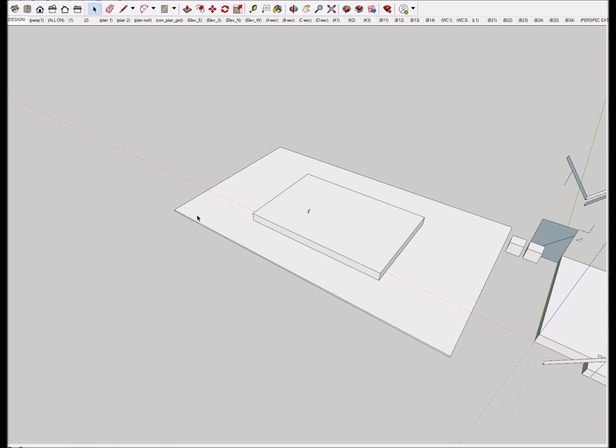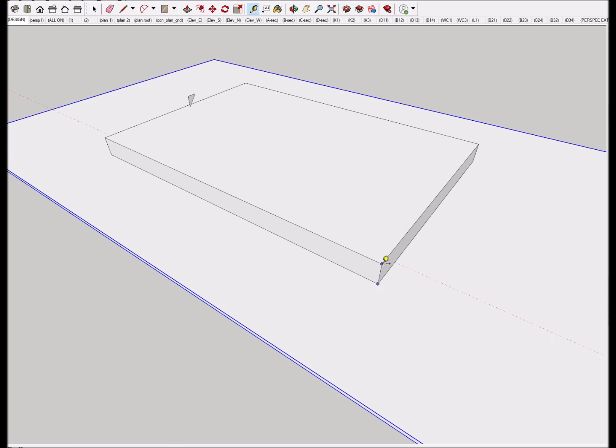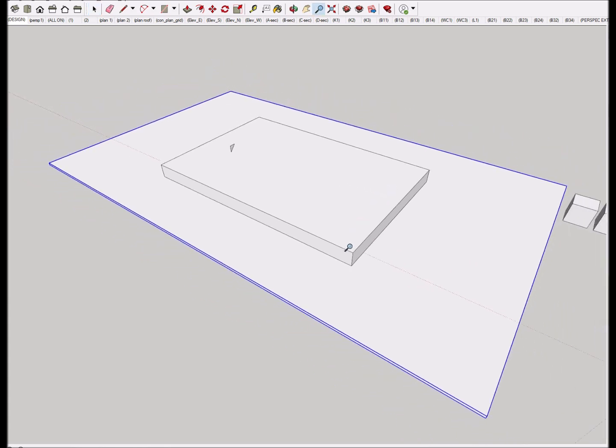First thing I did was I just created a ground surface. This is the outside, the outdoors, the ground level, the lawn, etc. And then I made a rectangular block, which is the start for our first floor, and I extruded that up to be 3 feet deep. So if we look, that's 3 feet high there. I made it 48 feet wide. If you look at the cursor, you'll see 48. And I made it, for now, 32 feet deep. And that's just our starting point. We're going to adjust this as we develop the mass in more detail.